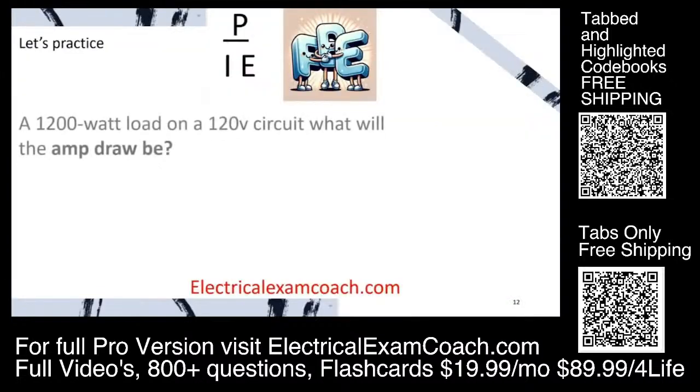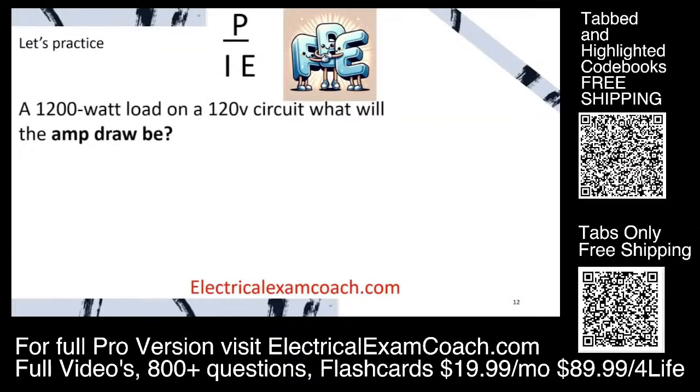In our first scenario, we have a 1200 watt load on a 120 volt circuit. What will the amp draw be? Well, we just plug in what we know. We know the wattage, and we also know the voltage, and we're trying to solve for the current. And just like in the previous formula, all we have to do is divide. So we divide it out, and we end up with 10 amps.